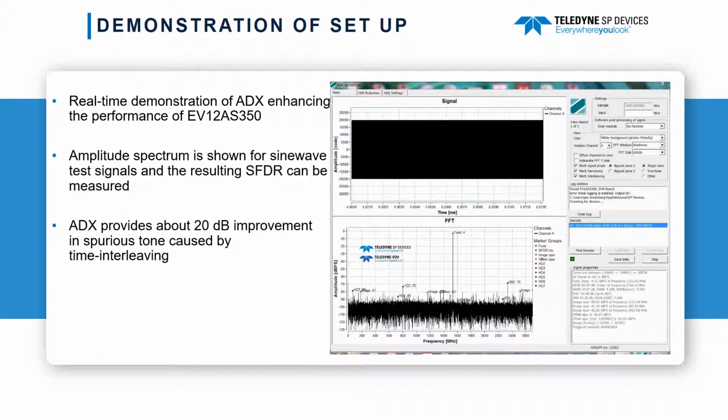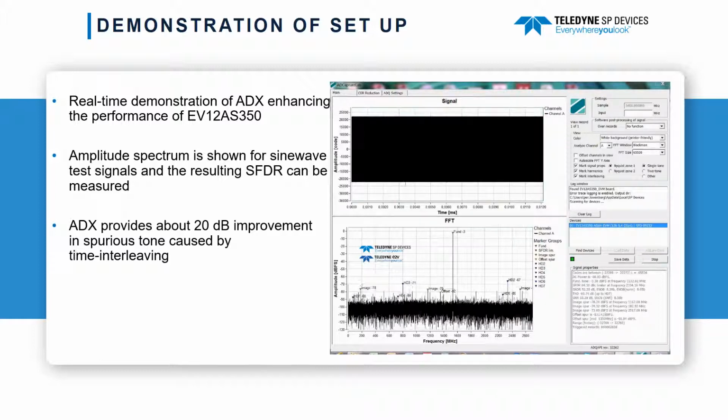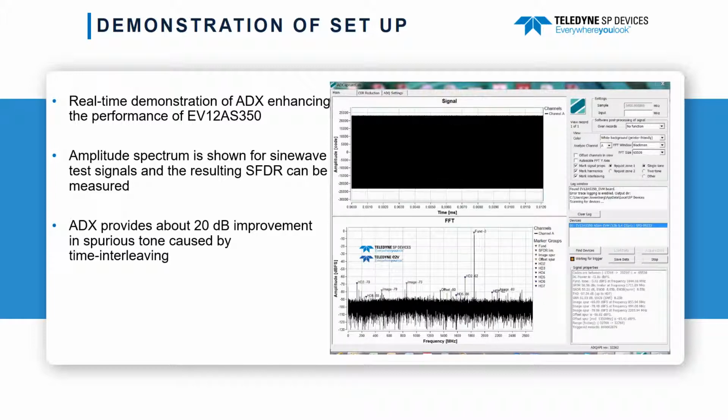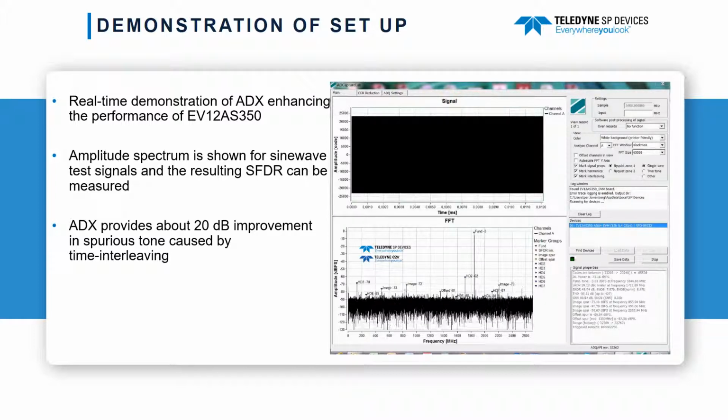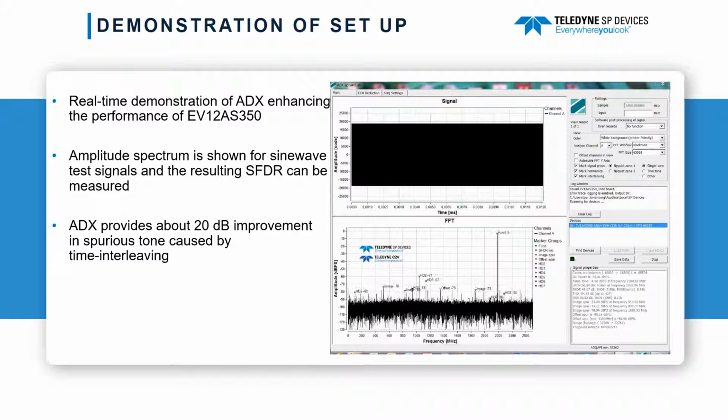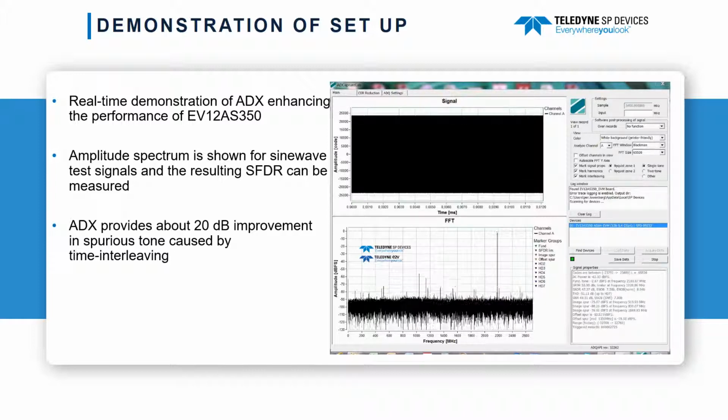Data is collected repeatedly, and from the measured amplitude spectrum one can see that interleaving spurs are below 70 dB fs across the entire sweep. When the aliasing spurs reach such low levels, noise that is uncorrelated between different ADC core references causes small fluctuations in the aliasing tone levels. SNR in these measurements is influenced by the wideband noise of the signal generator that provides the input signal across the entire Nyquist band of the ADC. With ADX, the SFTR of the ADC is set by the harmonic distortion.